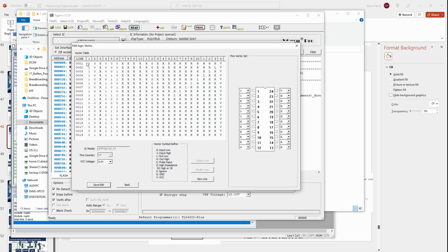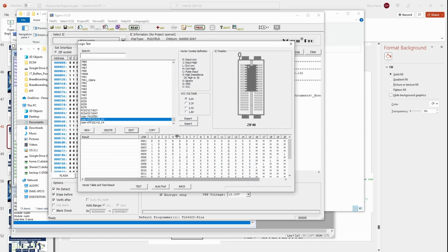What these rules here I've done is I've plugged in the various combinations of the read, write, and E signals and all the various address signals and which of the outputs we expect. So this is 0, 1, 2, 3, 4, 5, 6 down to 7. If this has worked properly, we should be able to just click test, and we can see that yes, this has succeeded. And if I went in and changed one of these rules, for example, one of these pin values here, then it would show me where that was not resulting in the right value. So what this effectively means is this should be working according to my rules, assuming I've got the rules right, and we don't actually have to test it in any other way.